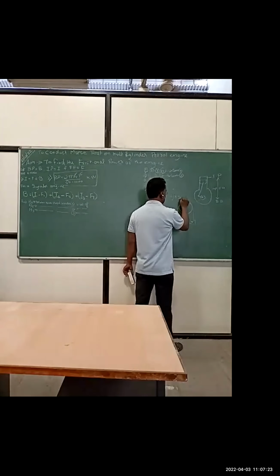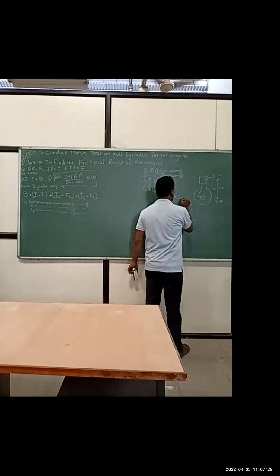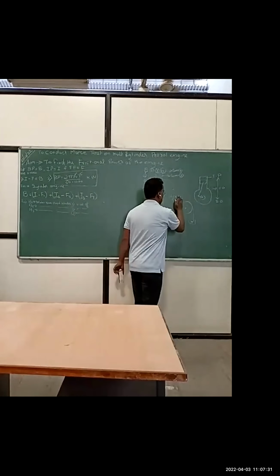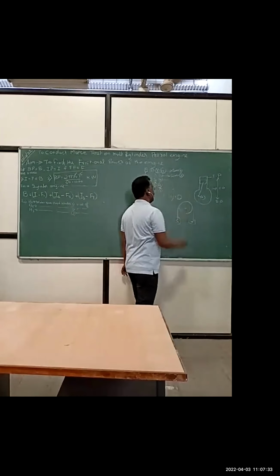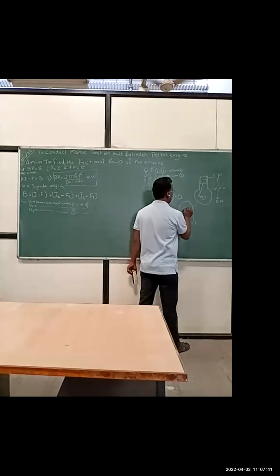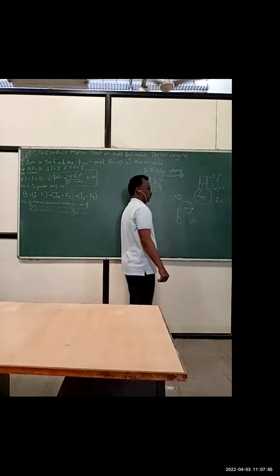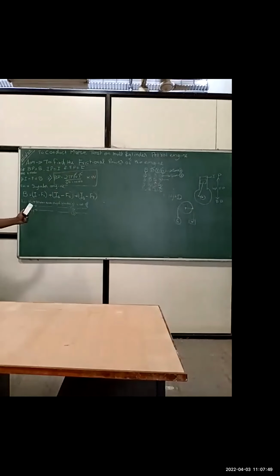And here S is the spring balance reading. Let the perpendicular distance be denoted by D, and the perpendicular distance will be this much, from the center of the pulley to the center of the rope. This will be in case of a rope brake dynamometer.